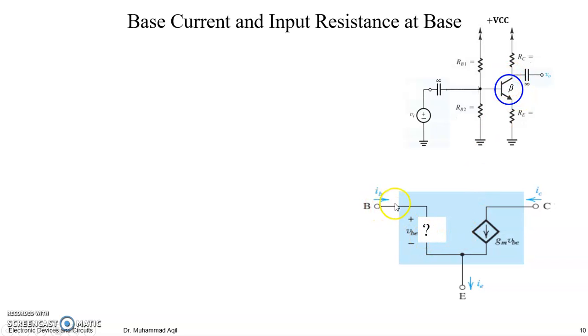So for a voltage and a current, we already have a linear relation, right? For a small signal, we would have here what? Let's see. We know that the total collector current divided by beta gives the total base current, right? And we already derived for small signals that the total collector current is nothing but the sum of the DC current and the AC current, right?